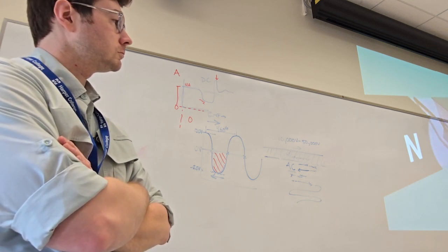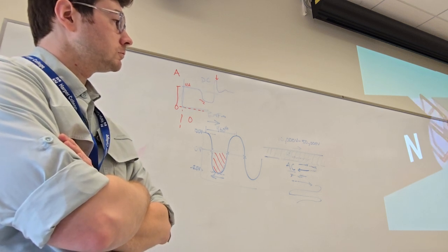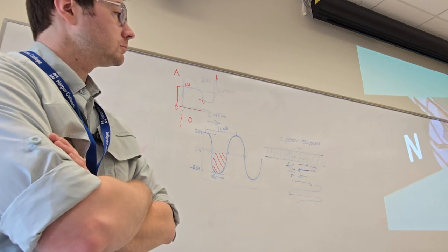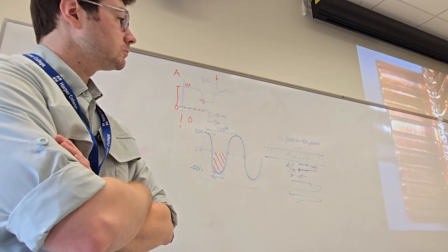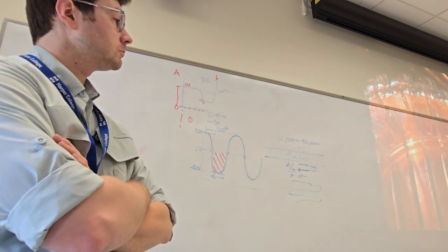This process will maintain a consistent direction of rotation of the loop. In order to achieve a uniform motion and torque output, the number of loops must be increased. The additional loops smooth out the rotational forces. A starter motor armature has a large number of conductor loops, and so has many segments on the commutator.